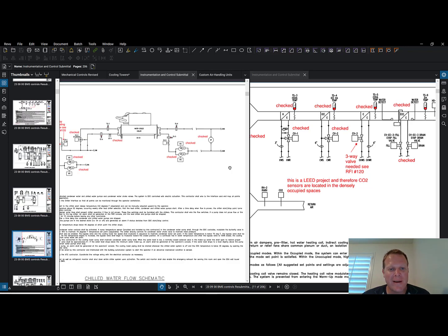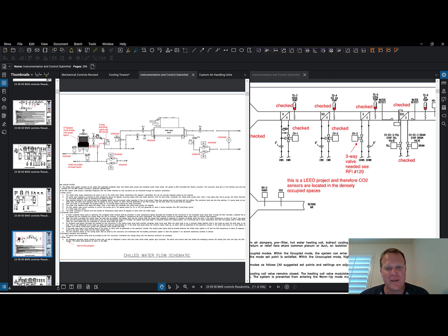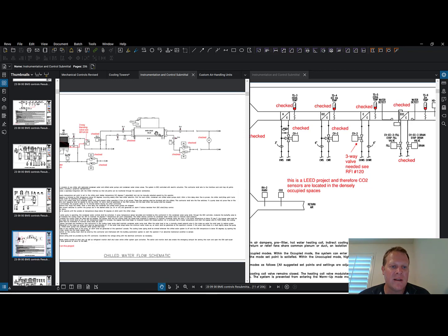Why the heck did you do all that, engineer? No, this is so common. This is like the larger version of what you see in front of your home. This is a really big air conditioning unit. I mean, a condensing unit basically is what it is, with a condenser and evaporator in it. It's got everything right there. It just needs a way to waste its heat. So this chiller can waste its heat through this cooling tower, and when it wastes its heat, it can cool off what's called chill water, and that chill water can go to a coil over here.